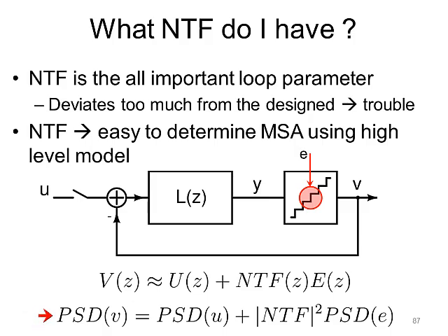And one common thing that a lot of people do is to just eyeball the spectrum. The idea behind that is the following. The output power spectral density consists of two quantities: the spectrum of the input signal plus the shaped quantization noise. And as we assumed earlier in this tutorial, it's common to assume that the quantization noise spectrum is white.